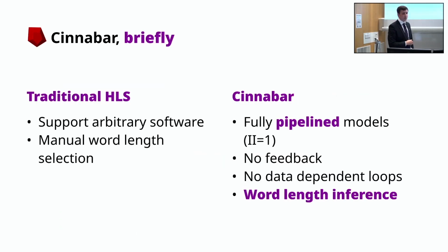Finally, briefly, I want to mention Cinnabar. It is a name that has appeared a little bit, and it is central to this as well. It is a high-level synthesis tool, which, unlike traditional high-level synthesis, which has to support arbitrary software and needs to do scheduling and dynamic loops and so on, where you also need to do manual word length selection, Cinnabar is restricted to fully pipelined models. So an initiation interval of 1, that means you can have no feedback in your model, you can have no data-dependent loops, you can have if statements, and you can have fully unrollable loops. But in doing so, we simplify the high-level synthesis tool so we know what we will get.